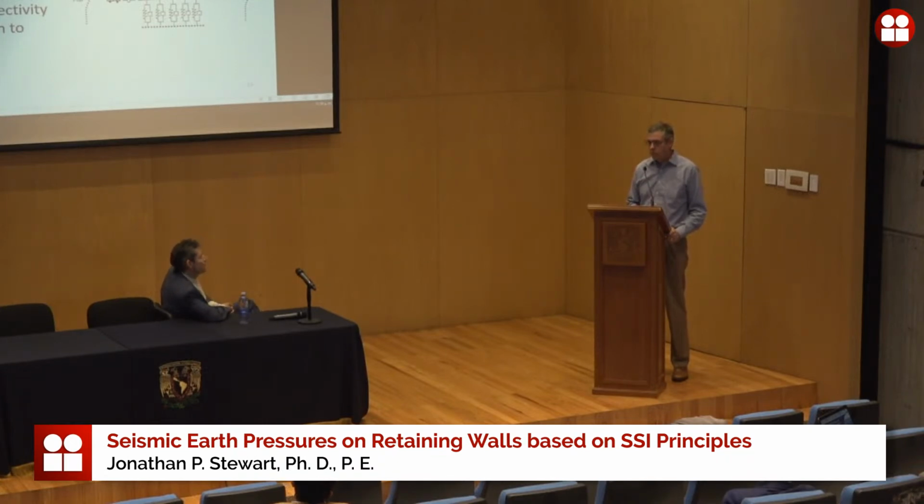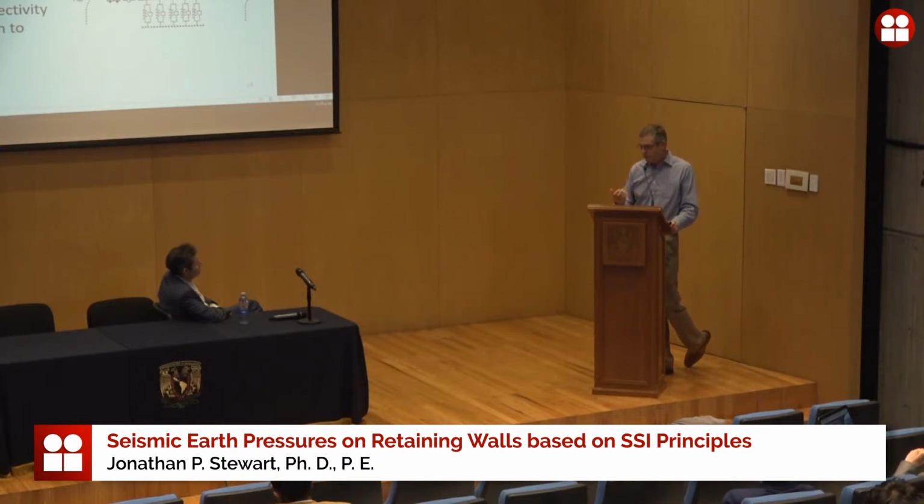The way that our solution was worked out, this is fixed. So if you go to the extra effort to model the flexibility, including piles, whatever, compared to the simple solution that I've shown, you're going to lower the pressures. So again, that was deliberate because we were aiming to have something simple that would be a little conservative, and by doing more work, the engineer will be rewarded for that extra work by lowering the pressures.